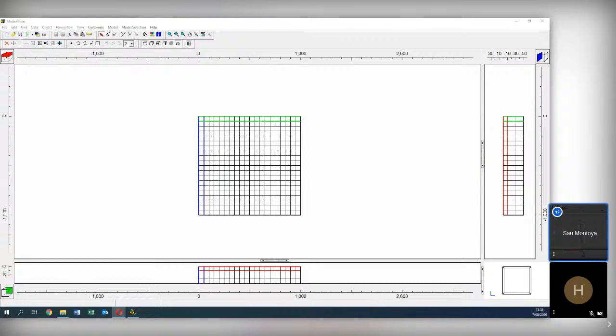In Modflow 6, you have confined and convertible, but the confined type is by cell, while in Modflow NWT it is by layer. So we are going to explain that in Modflow NWT because it will be easier for you, while in Modflow 6 it is more complicated. And if you are, let me show you.